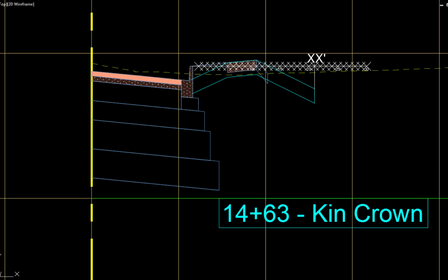If possible, within a reasonable distance, eliminate sags to prevent ponding. Stretch the vertical end line of the drive template and label to the desired intersection point. Since the driveway profile grid and reference line are block objects, they will not be included in the stretch.